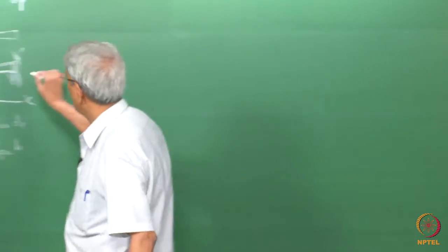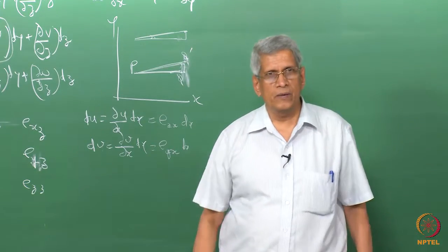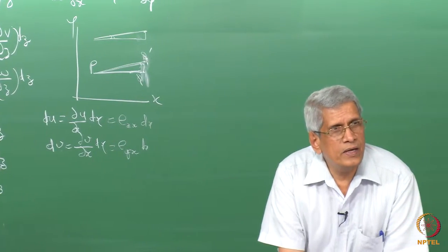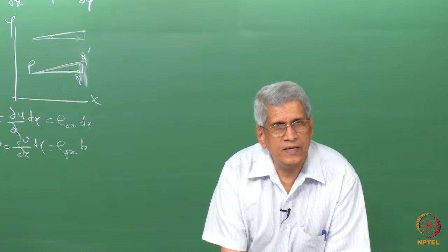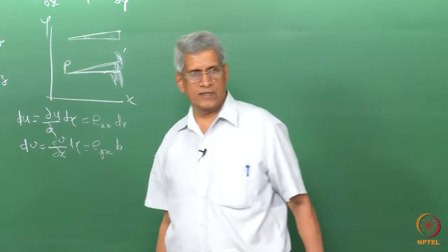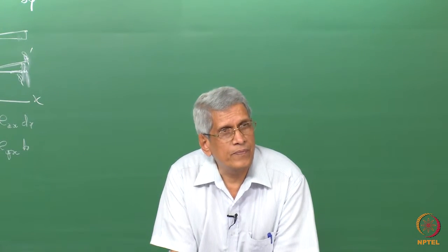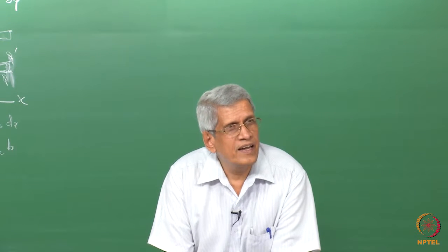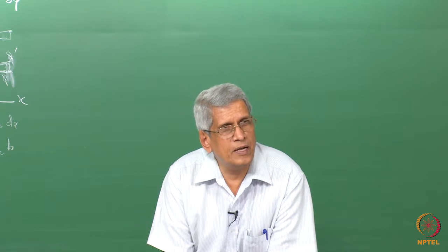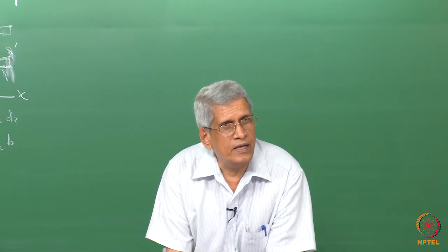It is a vector PQ, okay. The position of the vector after some elongation is in this direction, okay. Then the question which comes is that we can find out what is the component of extension in the x direction, okay. That is essentially nothing but a longitudinal strain, correct? And what is going to be the component in the y direction? That component could be just a simple rotation as well. So that means that this strain which we try to represent, yx, it could be a shear strain or it could be a rotation also. It need not completely represent, whereas Exx's definition is very clear. Whereas for all the other terms, when x is not equal to y, there is a problem.